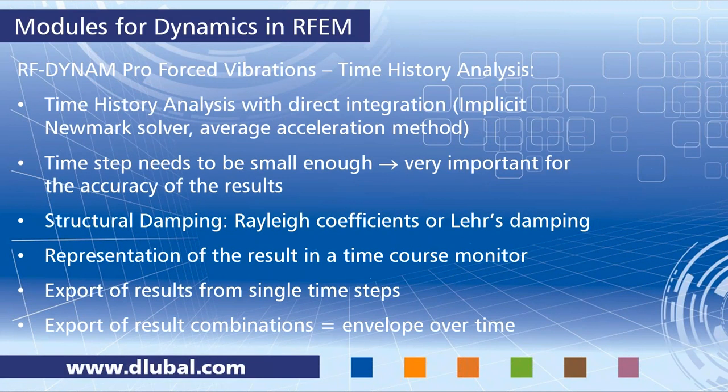As I said, we will have a detailed look into the forced vibrations, into the time history analysis. We have the direct integration implemented, so we use the implicit Newmark solver. There are different Newmark solvers available in the literature. We use the average acceleration method. You can have a look in the literature for further details. For example, Wilson's Structural Dynamics is just one book I can mention, but there are many good books available